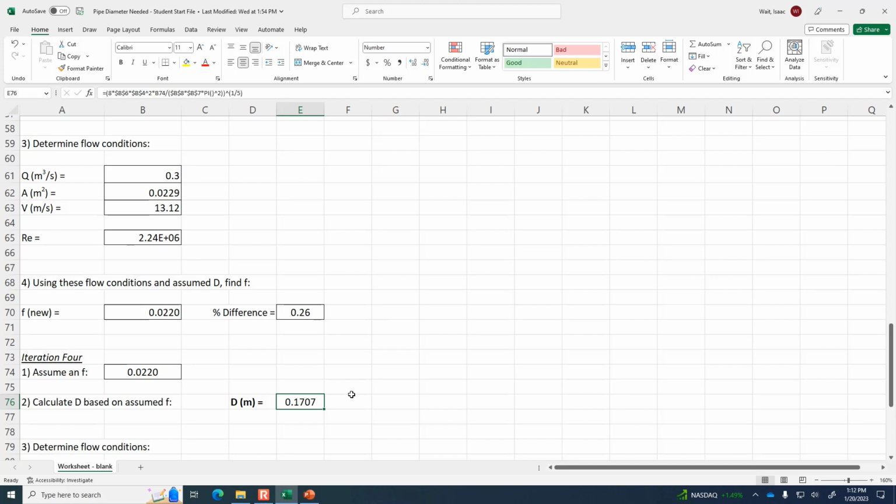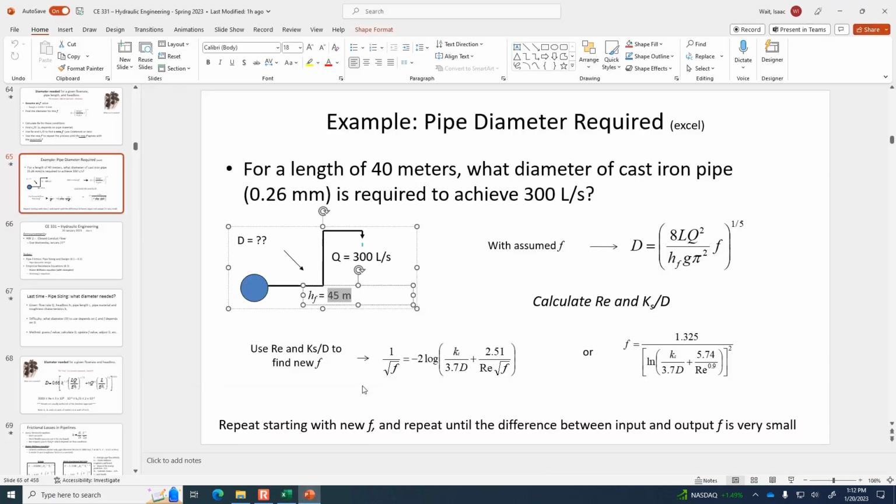Up. You're right. Why should we round up? Does that also have to do with the pipe friction? Pipe friction is greater for a smaller pipe. There's going to be more energy loss for a smaller pipe.